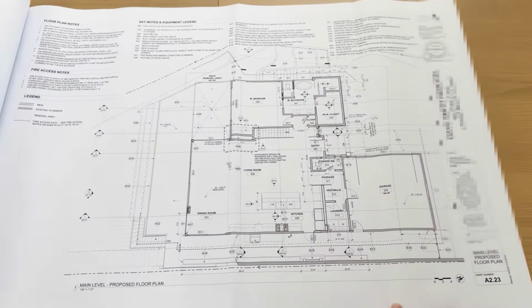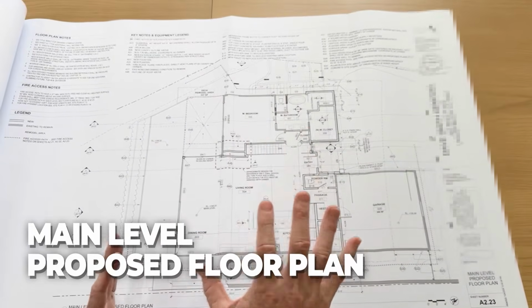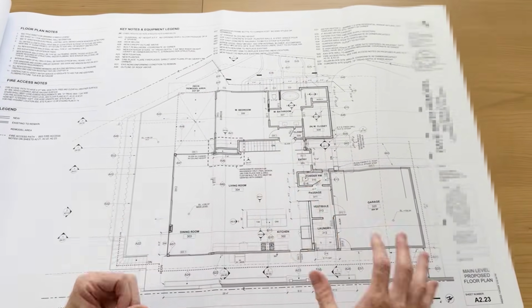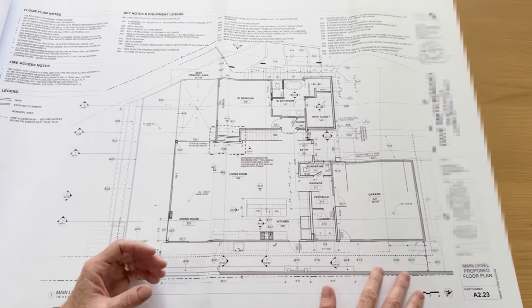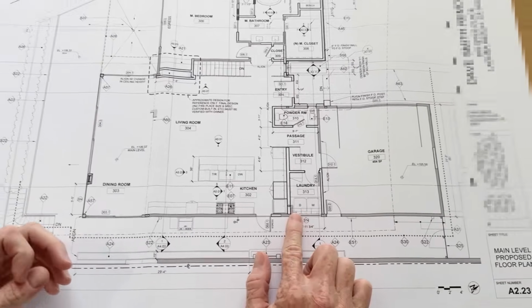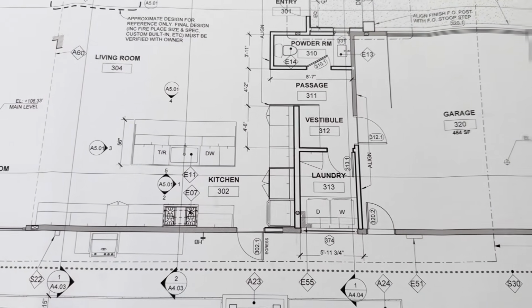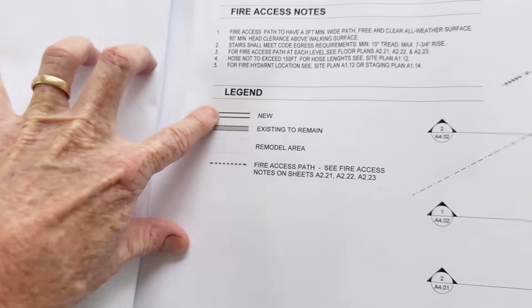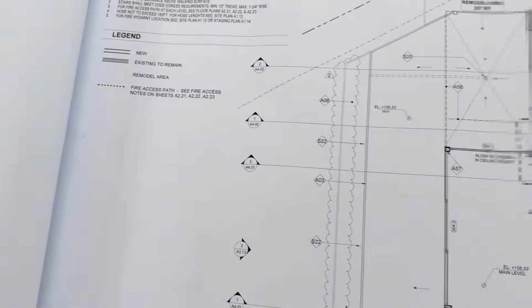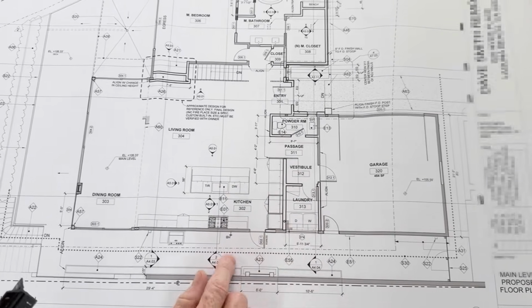Next page, main level. Okay, so a lot of information here, but if we just really simplify it down to each space, we'll be able to figure it out. So let's just take the laundry room, for example. He's indicating that there's a new wall running right through here, okay? So over here, you can see in our legend, this is a new wall. Any situations like this indicate new. So all these walls right here that are open, not shaded, those are new walls.